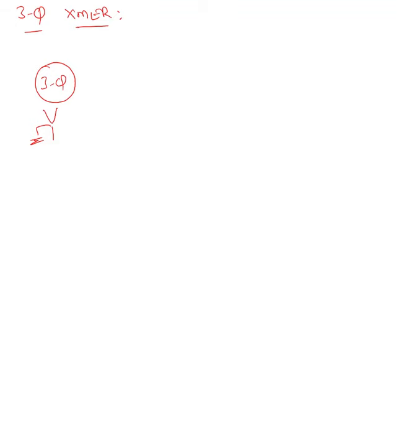Three-phase transformer. In this video, I'm going to talk about the three-phase transformer. All the power stations generate power by using a three-phase generator. Most of the time, that generator is going to be star connected because it needs a neutral. The neutral needs to be grounded for excessive current. In the case of an unbalanced load, the current is going to go through the ground.